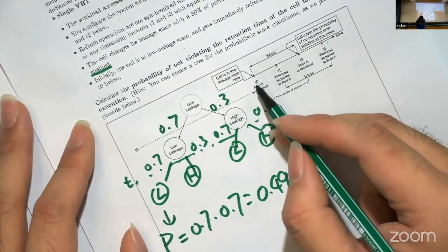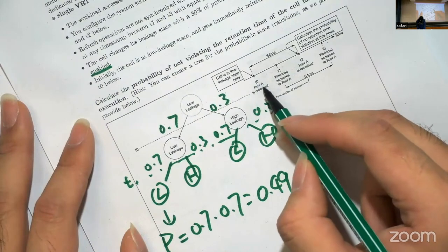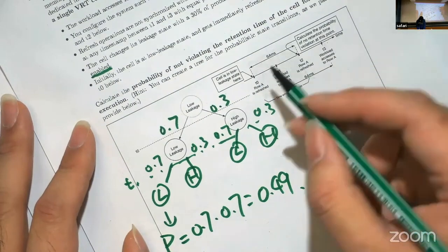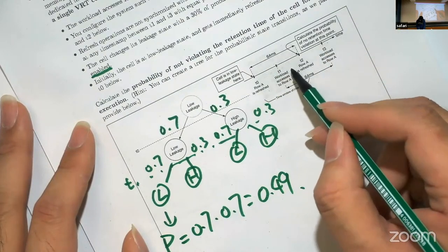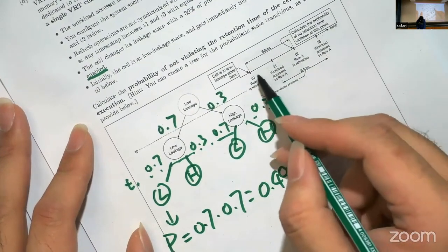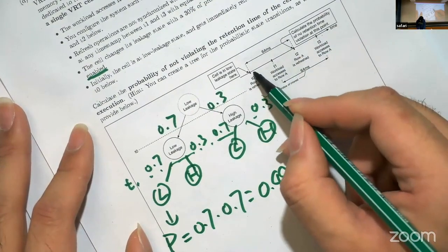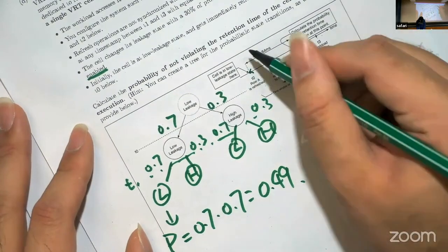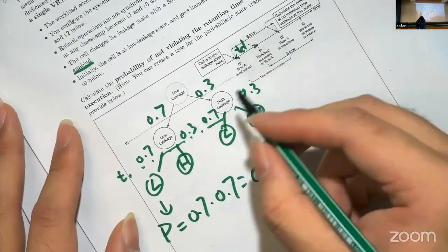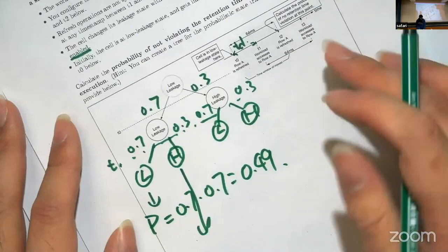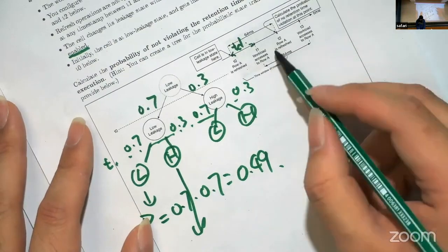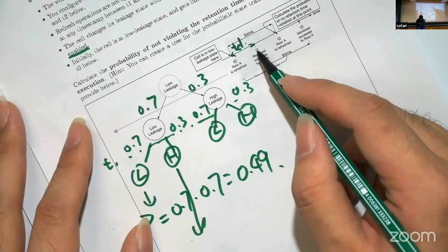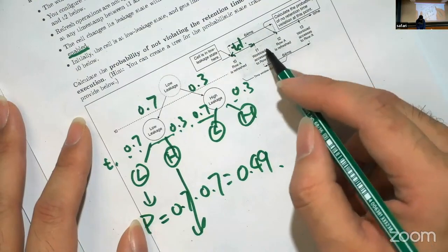And we also know that between T0 and T2 it's 64 milliseconds. Since this should be less than 16, the interval between T0 and T1, let's call it TD, should be larger than 48 milliseconds, so that T2 can happen at most 16 milliseconds after T1.